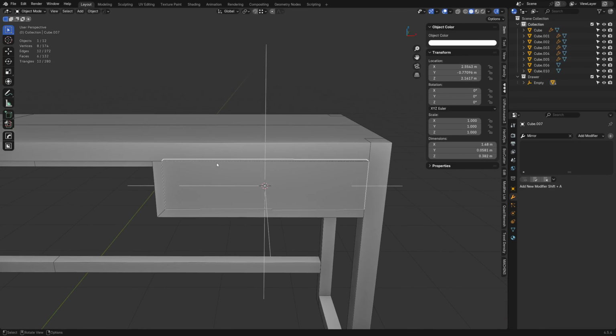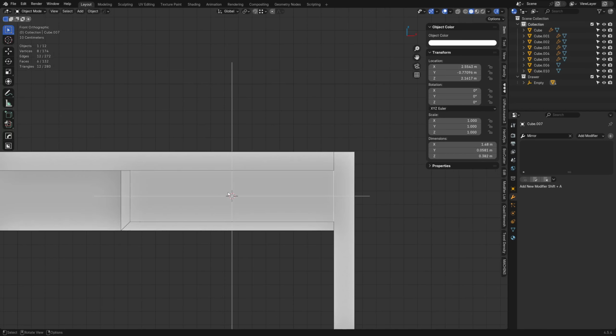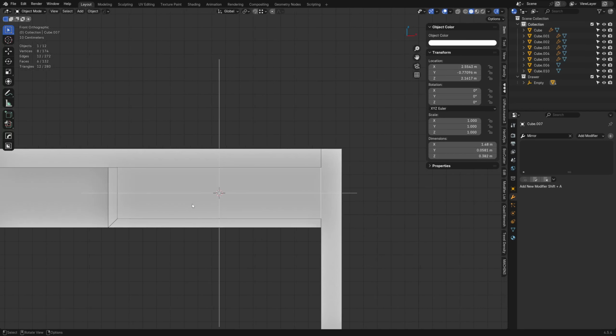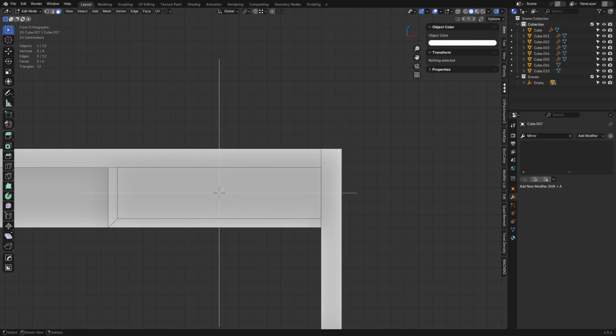This drawer has a cut in the front here. There's a couple different ways we can try to do this. First, if we've got this front drawer selected and I press K, well, go into edit mode. If I press K and C and I hit A, I can start doing knife cuts. Now you're going to have to hit K, C, A, and 5 probably to get this kind of behavior. And if you want to see the angles like you see here, you have to press S twice or something like that. That's annoying, right?